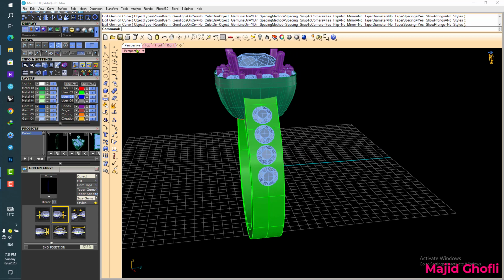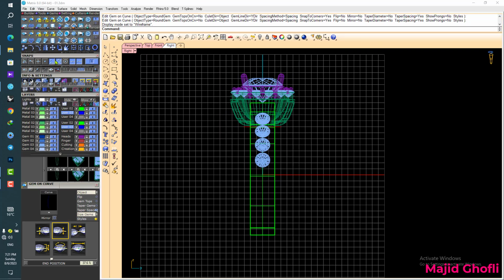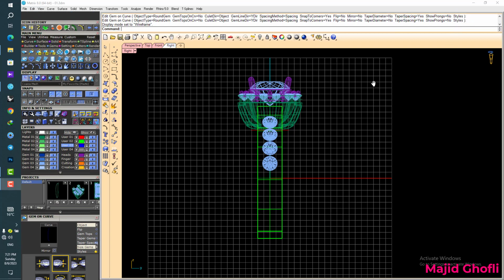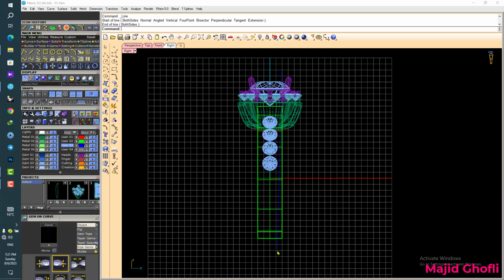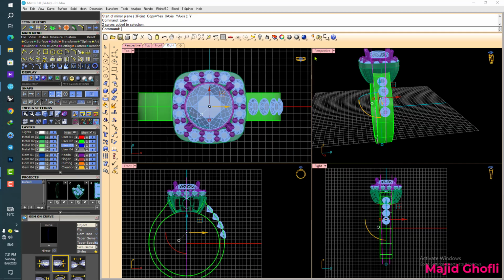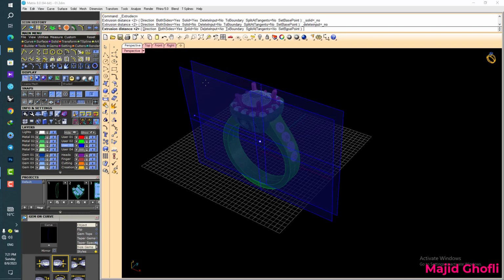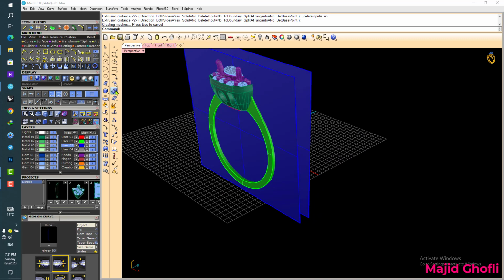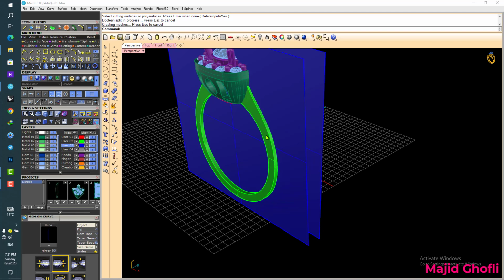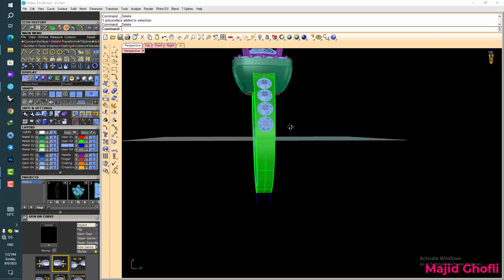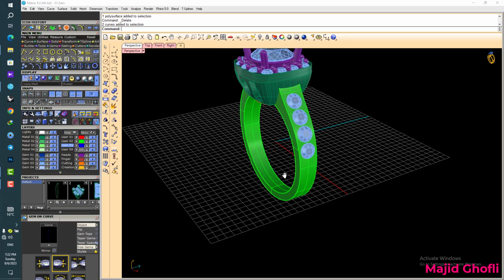After that we need prongs, or before prongs we can cut the arm. So go to the curve and use a single line, this point and this point, I think it's really good. Ctrl F1 for mirror, and again go to the perspective and use extrude and straight, both sides yes, and again go to the Boolean and Boolean split, this part and this part, yes, it's done. Remove the extra part and these surfaces, yes, it's almost done. Look at this guys, it's really beautiful.